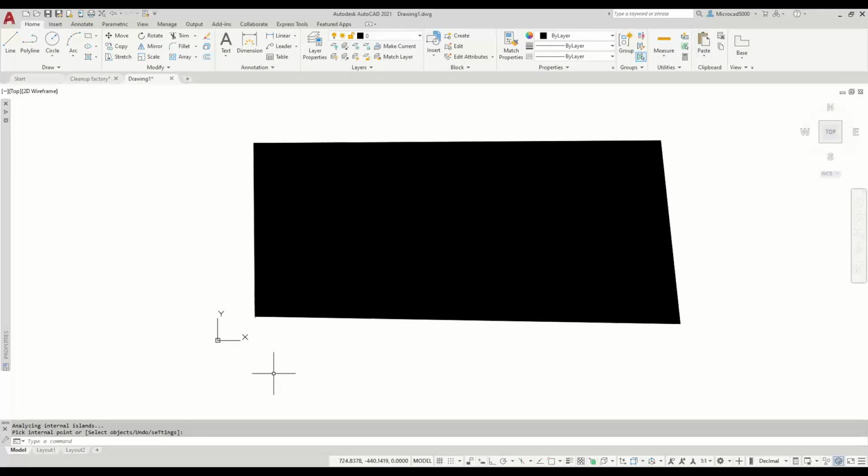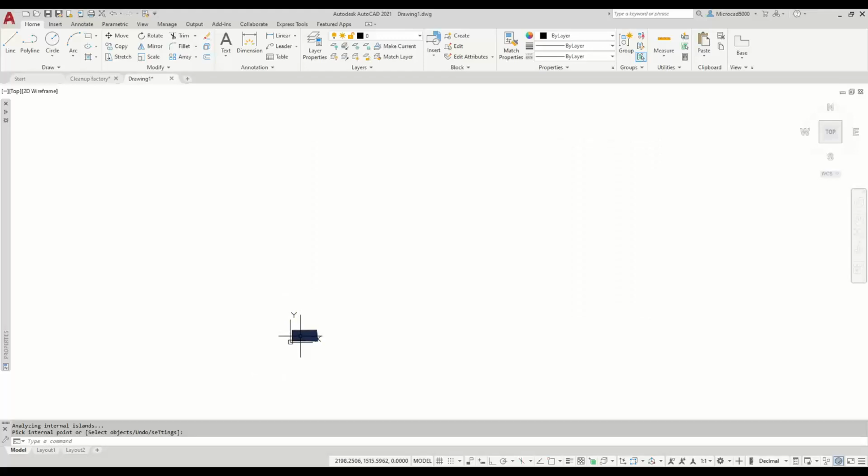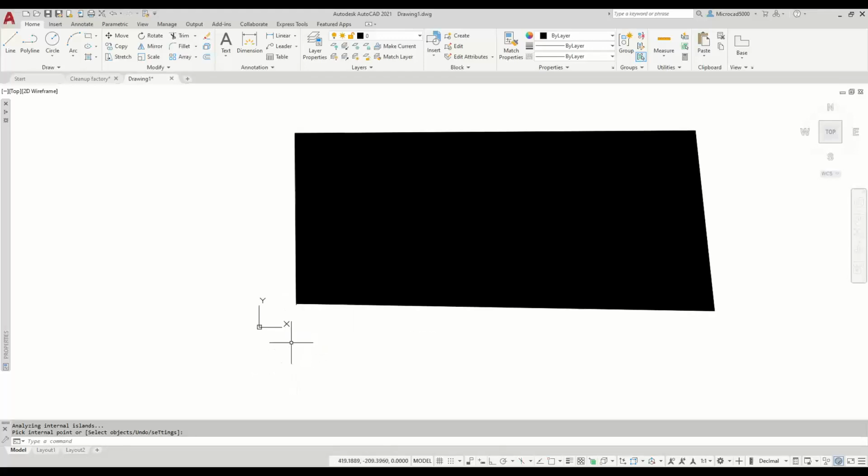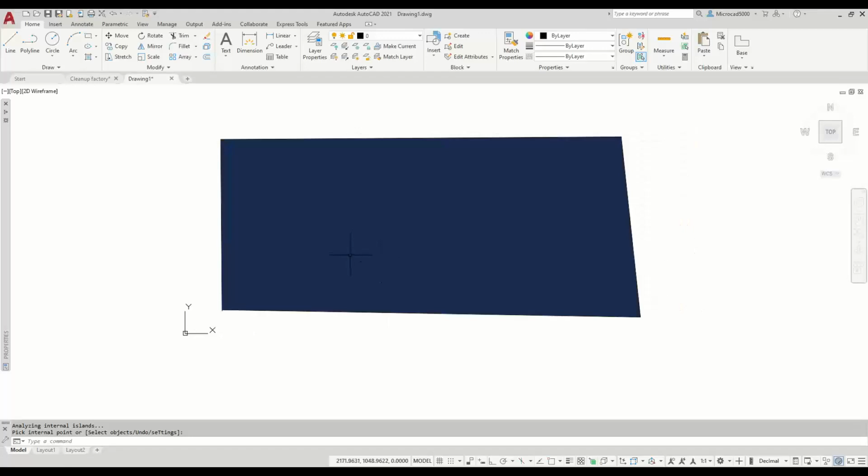What I sussed out here, and I worked this out from a customer's drawing, was that the hatch routine works on the resolution of the display, not the accuracy of your drawing. So as far as the display is concerned, at that zoom level, there is no break. At that zoom level, there is. So when you are trying to hatch in your shape and you find a break and close it, and you do a bit more zooming, you may be opening up other breaks around the profile of that hatch area. So you end up chasing your own tail and get frustrated, and it's a nightmare. So watch out for that one.